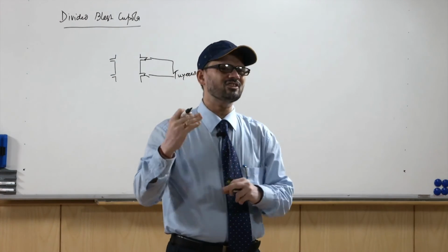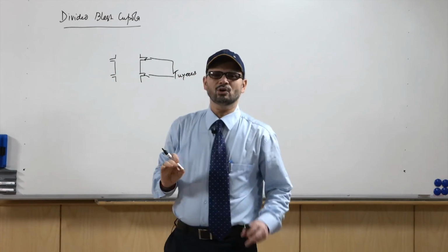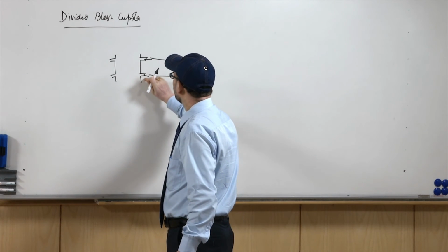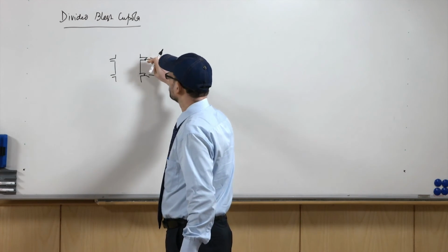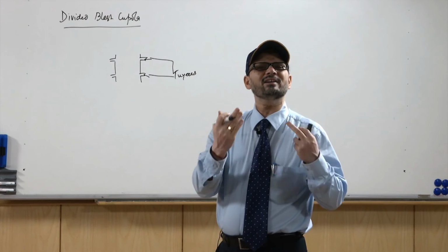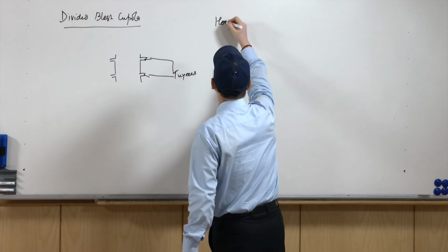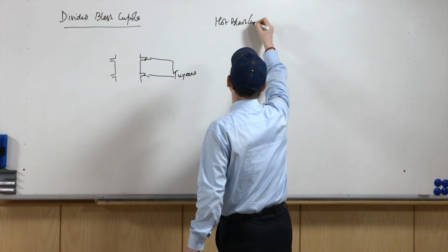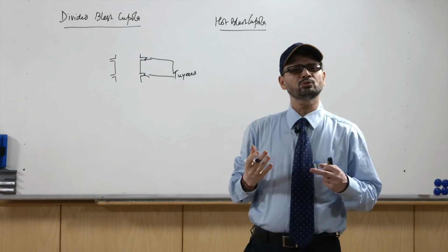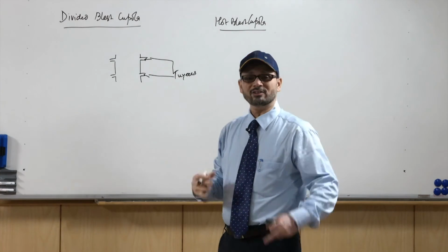That increases the efficiency and increases the metal temperature. So, you have to have an optimum height at which you put the first tuyere and then at the second height the second tuyere. Once the blast is divided, it is known as divided blast cupola. Similarly, there is another kind of cupola, the hot blast cupola. It has also been seen that if you increase the blast temperature, maybe up to the order of 500 degrees centigrade, the efficiency of this cupola increases.